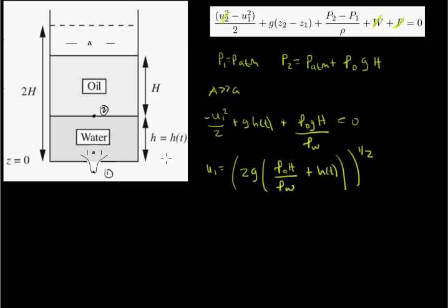And the next step is to look at this entire system and do a mass balance on it, because again we're interested in solving for time. So let's say that accumulation is equal to in minus out plus or minus source/sink. And if we view this entire box as our system, then there is no input, so there's no in, and there's also no source or sink. So we're just saying that accumulation is equal to the negative out.